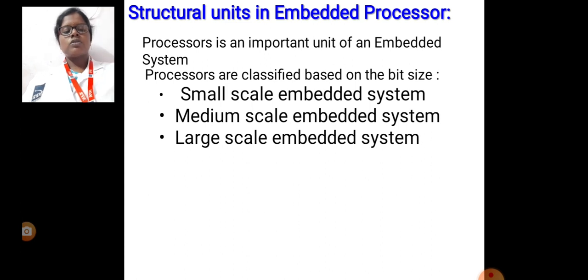It possesses the computational capabilities of a microprocessor, and also has multiply and accumulate units. A DSP provides fast discrete time signal processing instructions. It is not continuous, it is discrete time signal processing. It has a very large instruction word, VLIW, and processing capabilities.